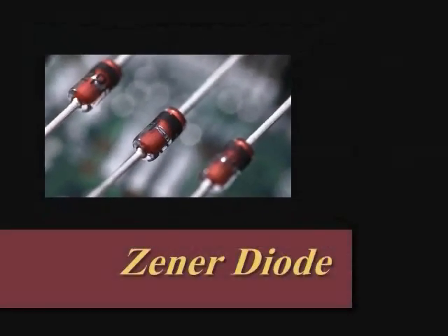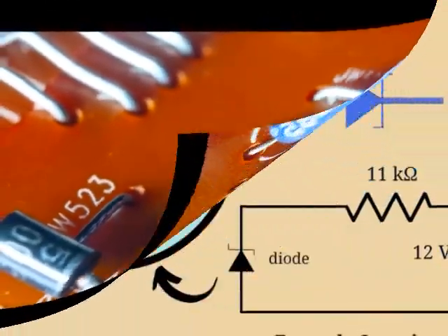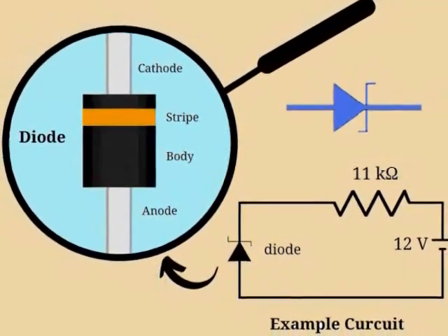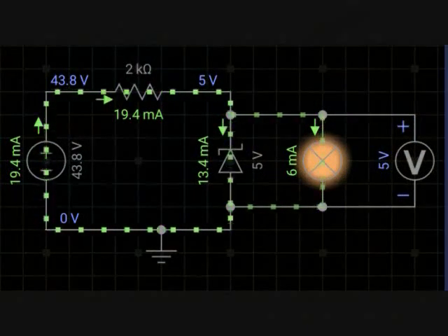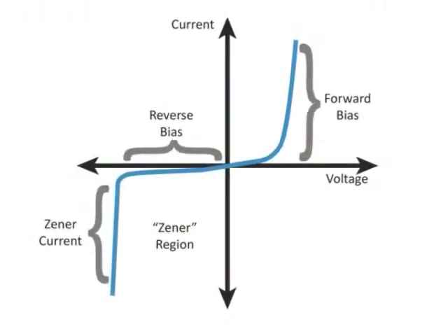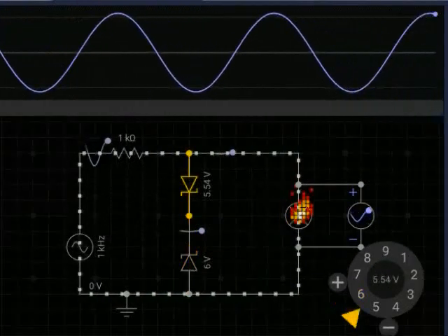Zener diode. A Zener is a type of diode used in the reverse region, meaning that in addition to passing the current in the direct mode like other normal models, by applying a fixed and specific amount of reverse bias, it passes the same current in the opposite direction. In fact, the main use of Zeners is in reverse bias mode, where they pass a large current for a nearly constant voltage.